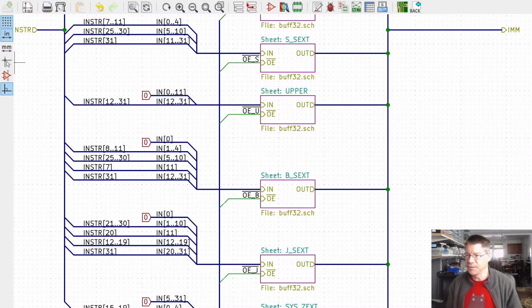What about the NOT gate delay? Yeah, I think what you're talking about is the NOT gate internal to the buffer. If that's the case, the timing in the data sheet is basically from that input to the output, so that includes the NOT gate delay, if that's there.